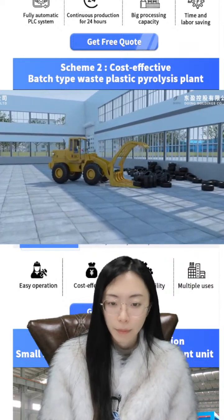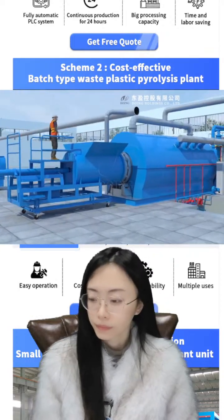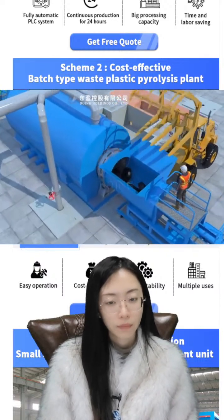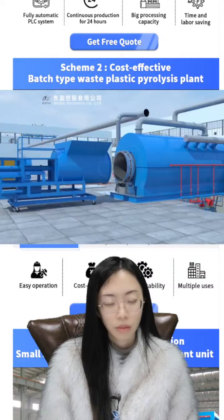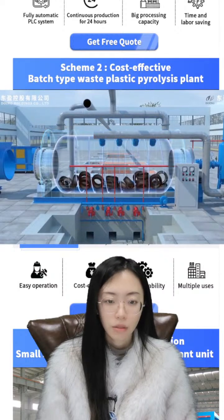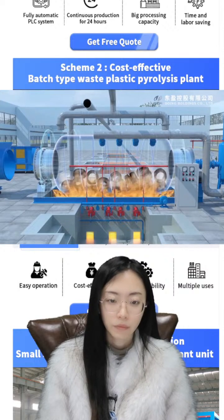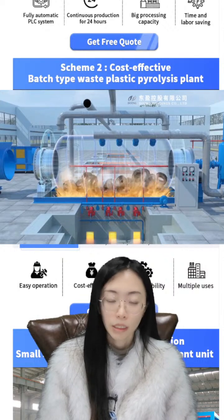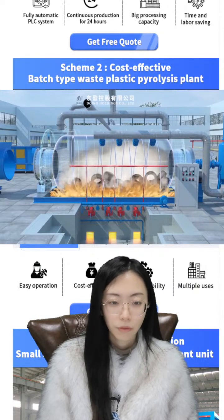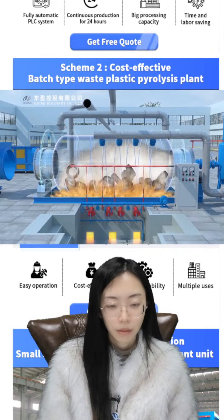This is the feeding step. This example is for the waste tire. We can also process household waste, oven bags, plastic bottles, or some tubes or plastic, except PET and PVC, which are not suitable for the pyrolysis working step. All the other plastics can be used, like PP, PE, PS, ABS. If we get pure plastic, the oil yield can be nearly 90%.